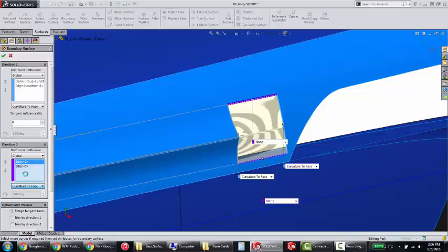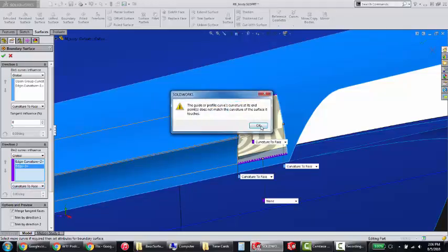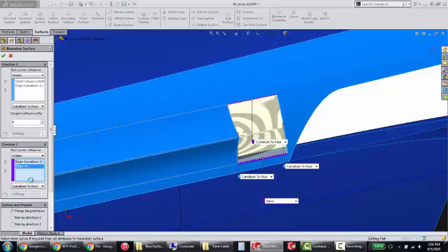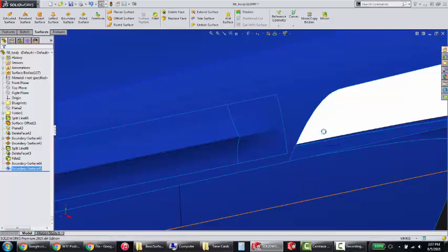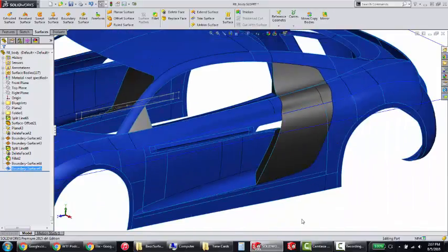You'll see that as I'm going through here, it does take a little bit of time to get through all the clicks. This last face gives me a little bit of a warning about whether the curvature is going to be able to be maintained. That's because we might have curvature starting to push in from all directions, so it makes the surface undulate a little bit, but I can't really see it visually. So there we go. Got a character line on a surface.